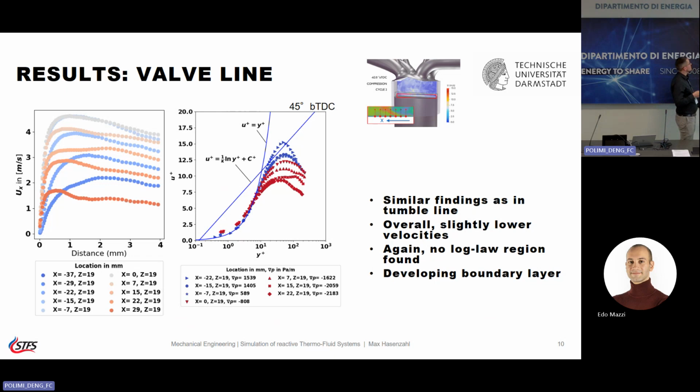Just as a small sanity check, if we move towards the line bisected by the valve plane and the piston, so a little bit out of center, also going from right to left, from exhaust to intake side, you see a very similar picture. You have still acceleration. It's a little bit slower in this region. Acceleration, deceleration, and detachment, eventually going from right to left. And again, you find no log law region. It's simply not present.